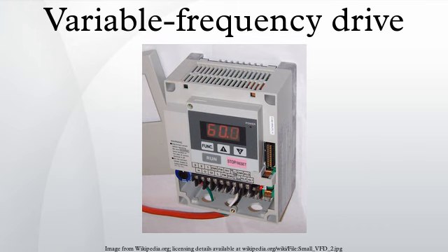Motors that are designed for fixed-speed operation are often used. Elevated voltage stresses imposed on induction motors that are supplied by VFDs require that such motors be designed for definite-purpose inverter-fed duty in accordance with such requirements as Part 31 of NEMA Standard MG1.